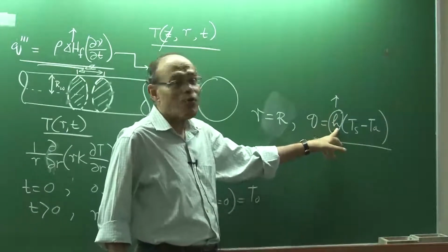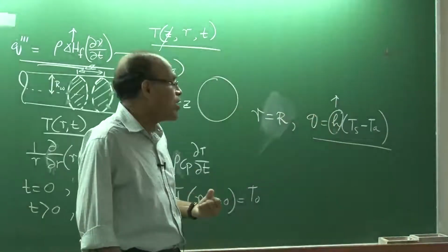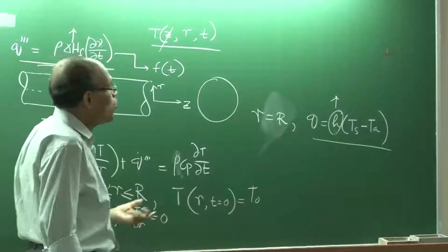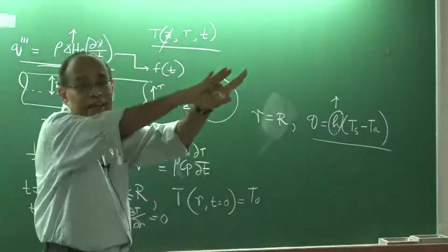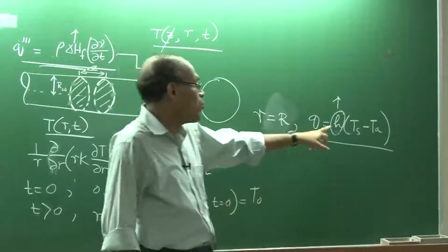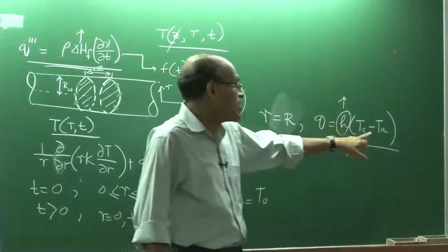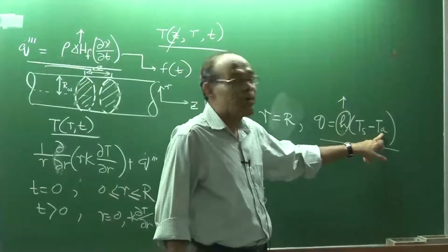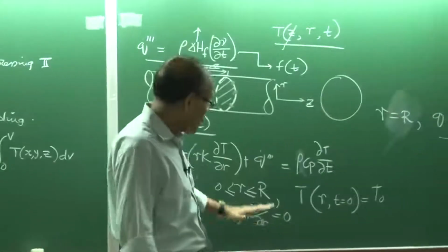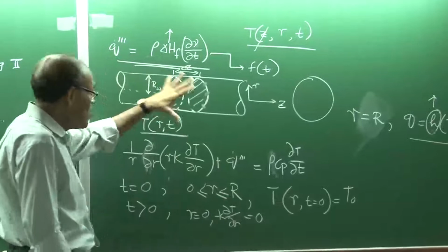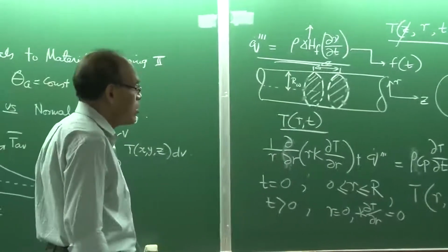So, you should be able to pick the right kind of forced convective correlation, and then from that, based on the velocity of the air, the properties of the fluid, etc., you should be able to compute this h. And this T ambient could be the ambient temperature, which is the room temperature. Therefore, all the boundary conditions will be known, and you should be able to solve these equations in order to find out